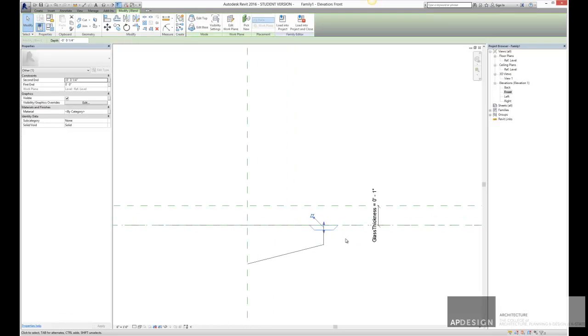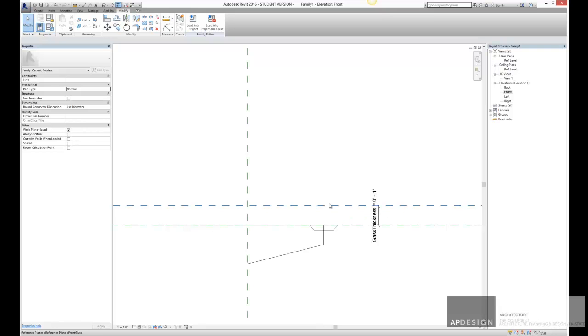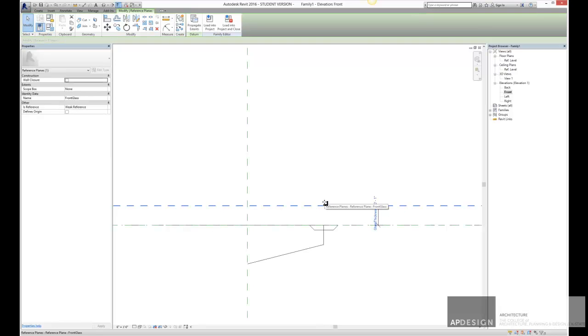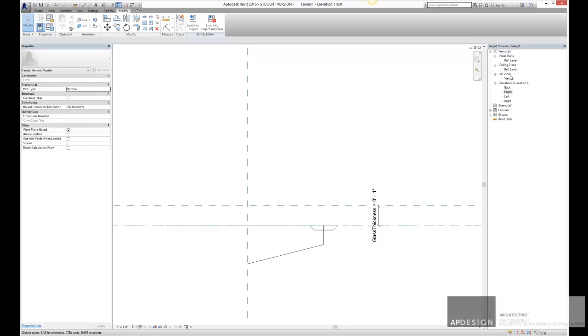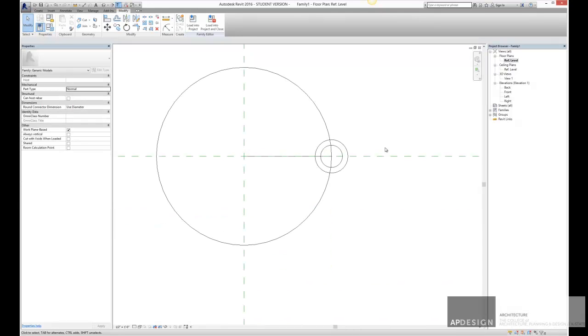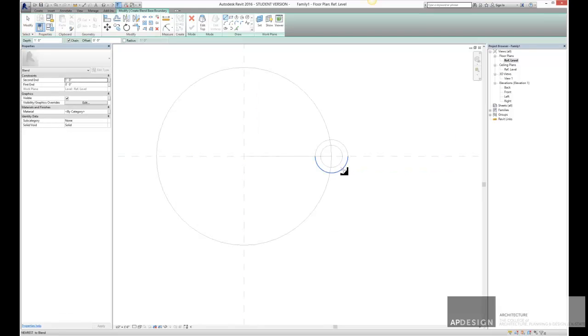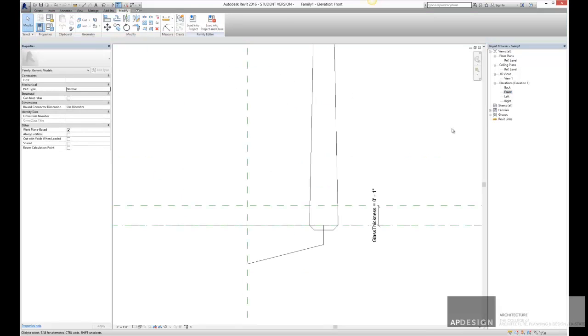And now let's do the top clamp. We'll go back into the floor plan and create a new one. So blend again, and we'll select the lines that we had before. What I did was I grabbed this pick lines, and I'll say now edit the top, pick those and say OK, and let's go back to the front view and we'll see this crazy thing.